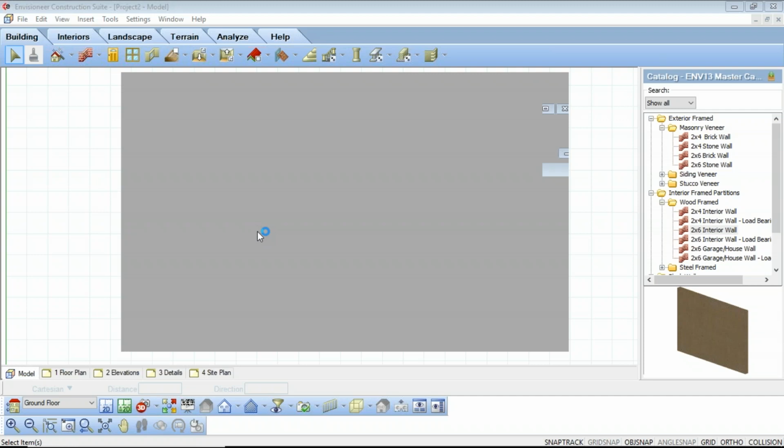It would depend on a couple of variables. One, if you want a quantity to be different, so if you want to bring up a quantity for the detached building separately from the ground floor building, then yes, I would create a new location called detached building, but base it off of the same measurements of the ground floor or slightly different variables in height. You could do it that way. You could leave them on the same location and then adjust the building afterwards